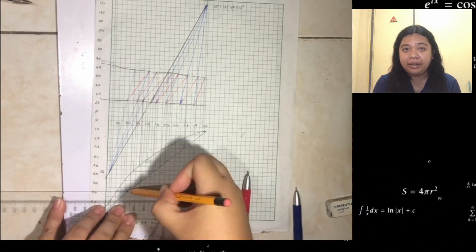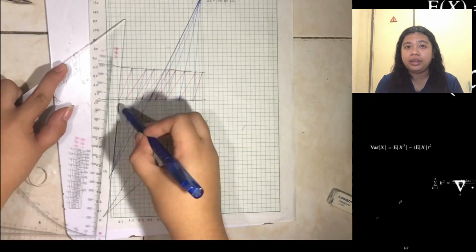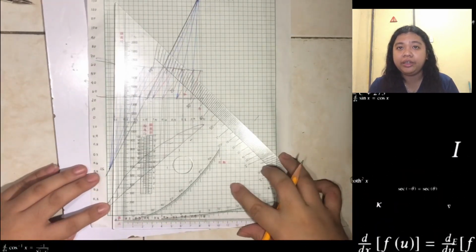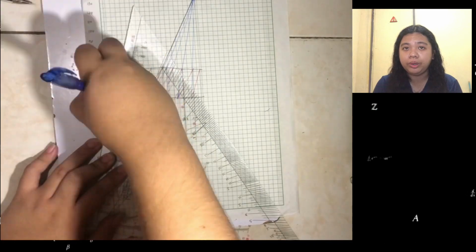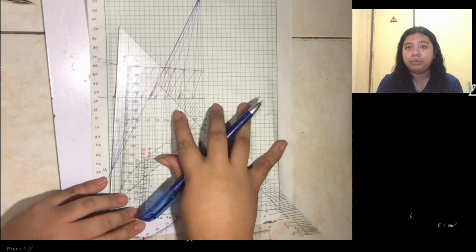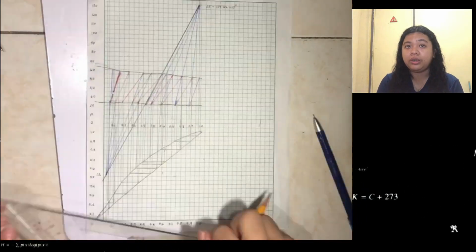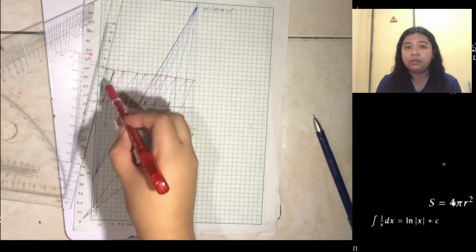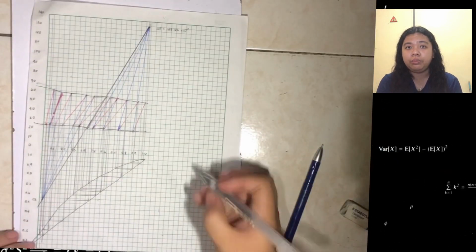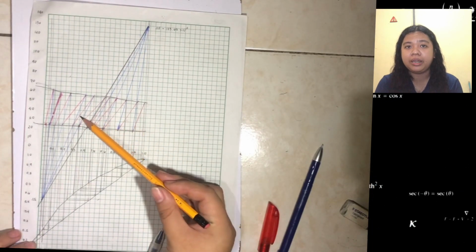Create an operating line again from delta S, intersect it with the HL point and extend it to HV and create a point. From the HV point, create a vertical line to the 45-degree line and a horizontal line to the equilibrium and back to the HL line. Create a tie line from the HL point to the HV point. Repeat the process until it reaches XW, which is equal to 0.01. The number of tie lines will be the number of stages. So in this problem, using the Ponchon-Savarit method, by counting the tie lines, the distillation column has 11 stages.